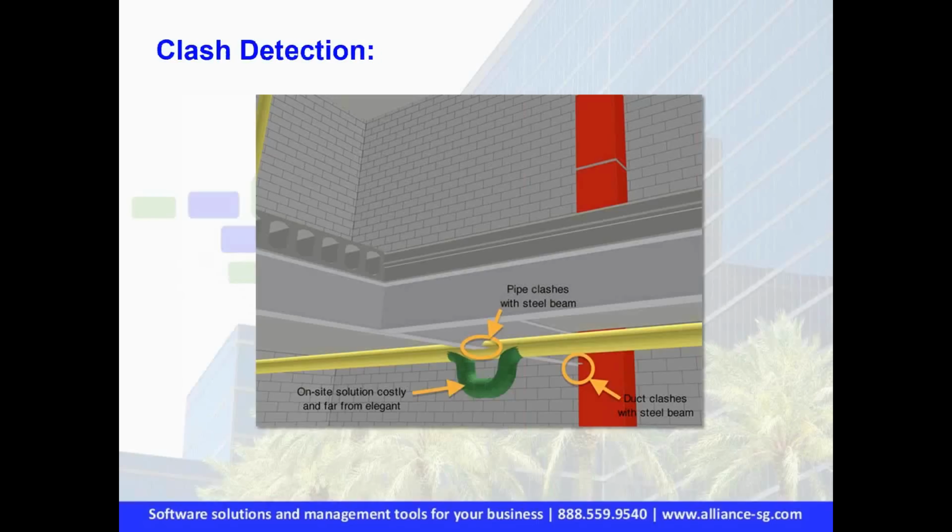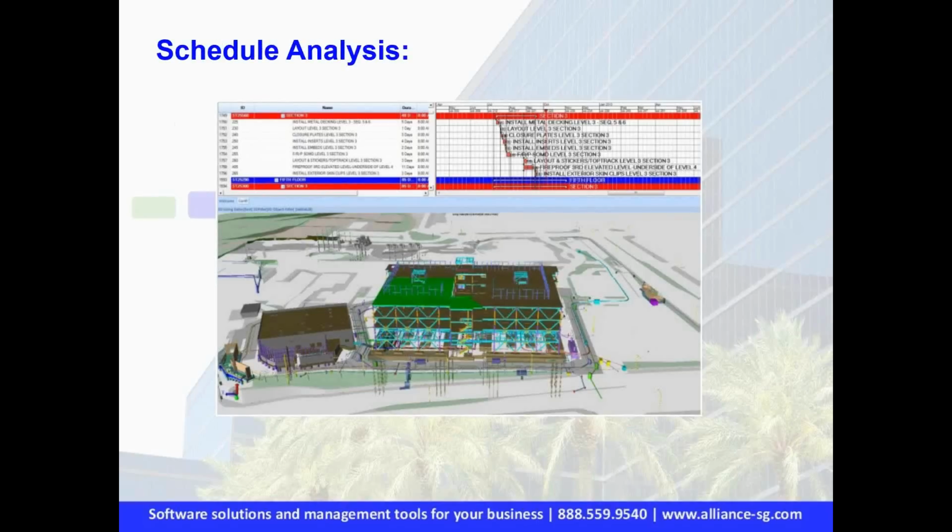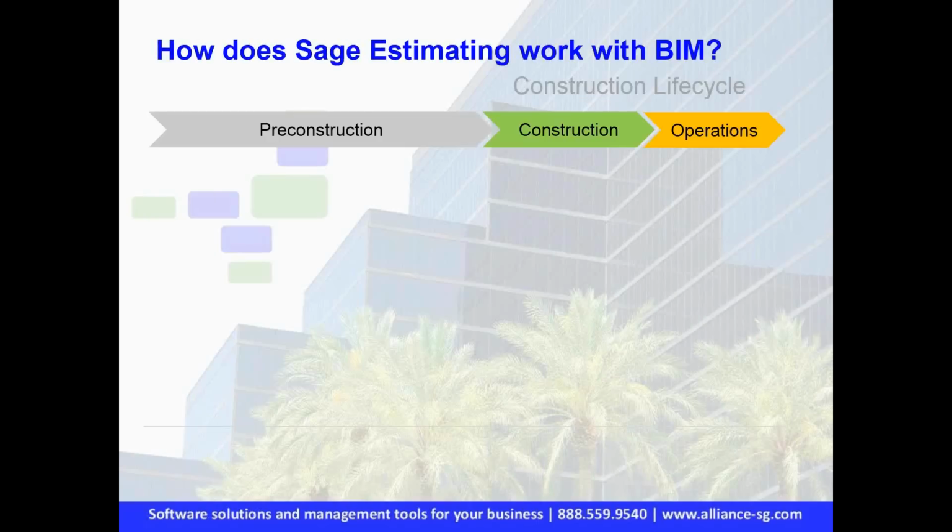If you notice, here's a couple of slides: the energy analysis off of the model that can be performed. You'll notice here there are clash detection tools. I referenced Navisworks. If I come in here, this is that application called Synchro. Synchro connects your model objects to the P6 schedule, so now you can visually see your building being built. And if your schedule applies costs and resource information to it, you can also visually cash flow and see where you should be. So it's a very valuable tool.